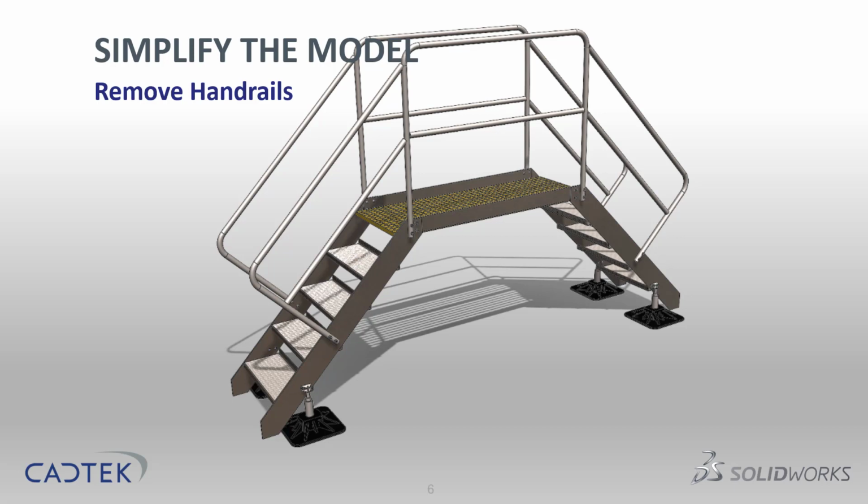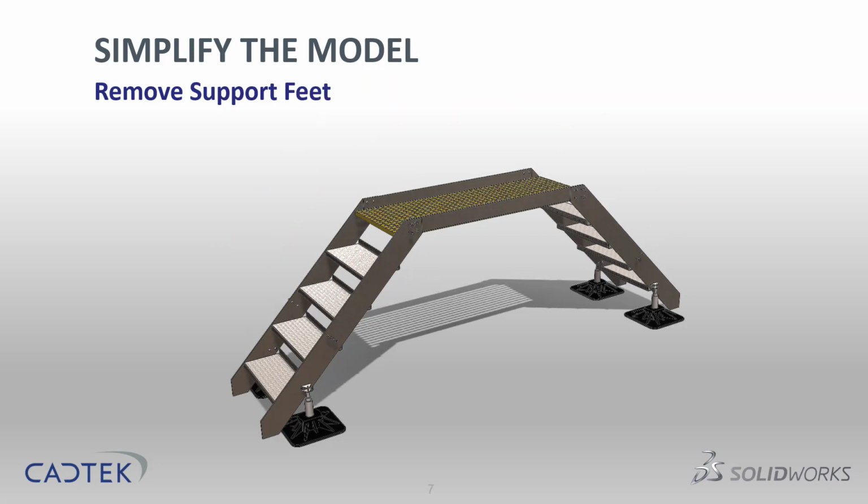So how did I go about simplifying this model? Well, for starters, I don't need the handrails in this design. They're not that heavy, so they're not adding to the overall weight of the structure, and they're not doing anything structurally. They're not making the support structure any stronger. So all it would do is just slow up the actual solution time, because the model will have to mesh it and check to see, but it's not going to give us anything extra into our design. So I suppress the railings.